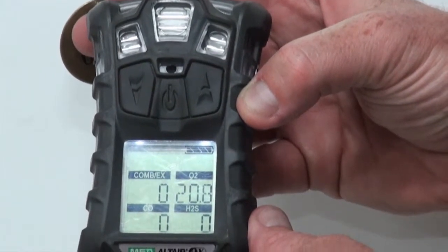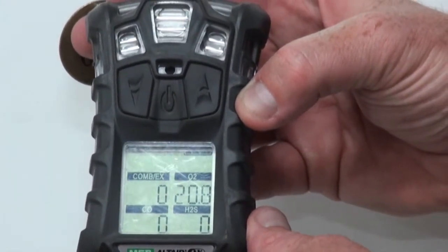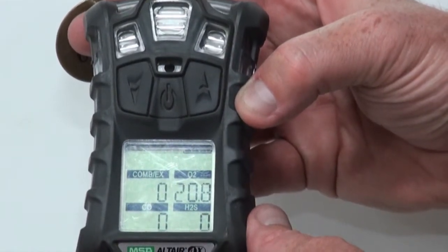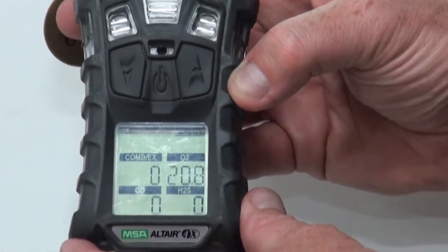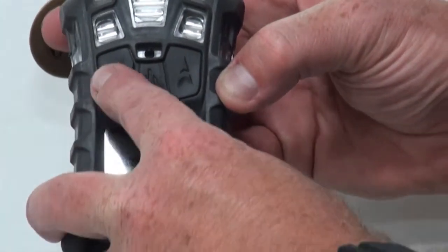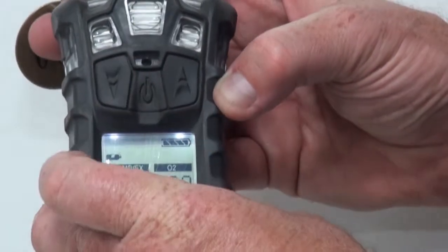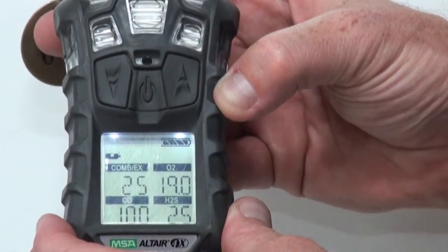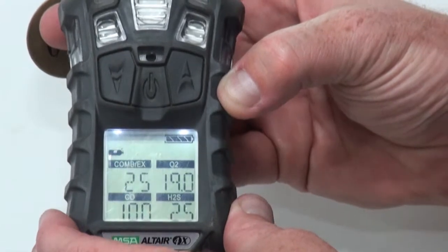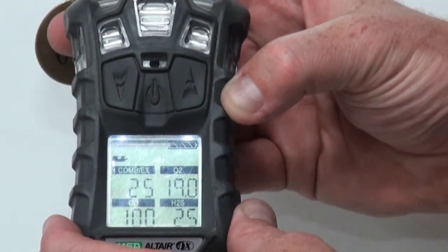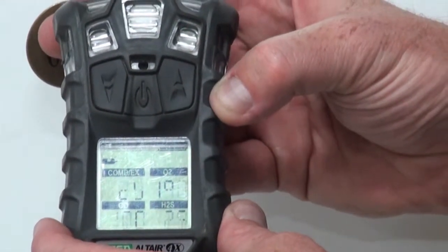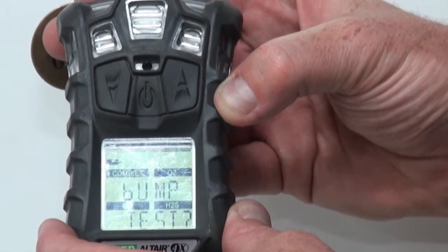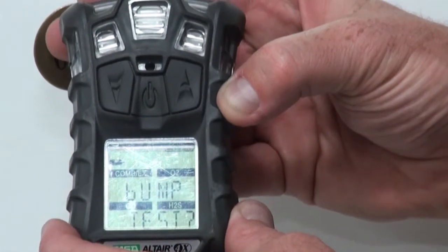Remember not to do fresh air sampling tests if the monitor has any potential for exposures or hazardous components in the atmosphere. Once you're in sampling mode, you have scrolling buttons that will allow you to access other screens. The first screen we can access is the bump test screen. Remember that we want to perform our bump tests in the mornings, exposing the monitor to a specific concentration of sampled gas and ensure that the findings or the results are within the allowable limits.